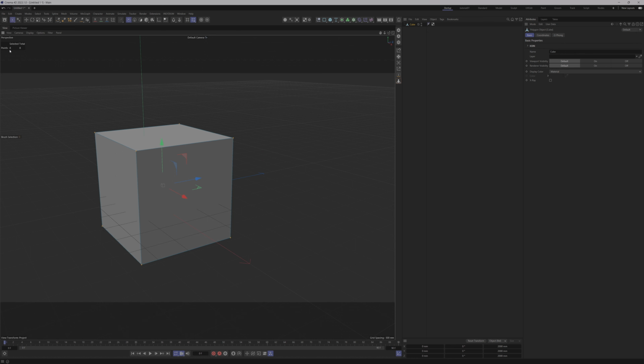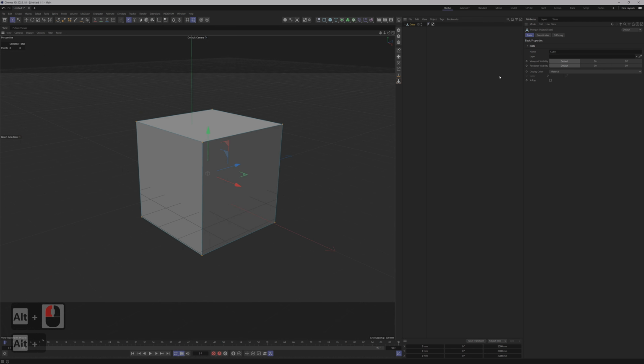It's selected 8 out of total 8 points. That's because when I go to the toggle visible only for the brush selection, you can toggle this on and off. That's what we just set up. Alt tilde. It just toggles between on and off.